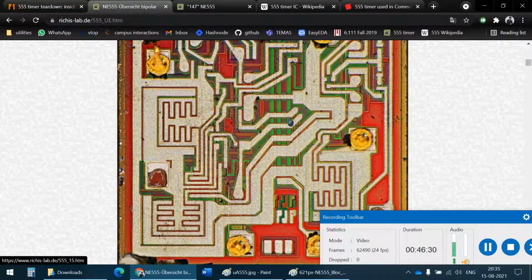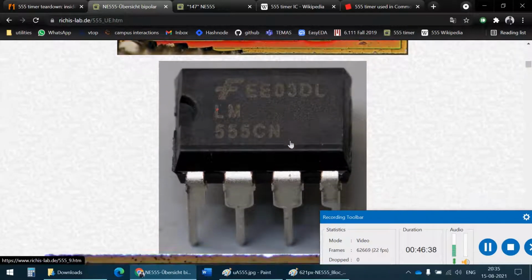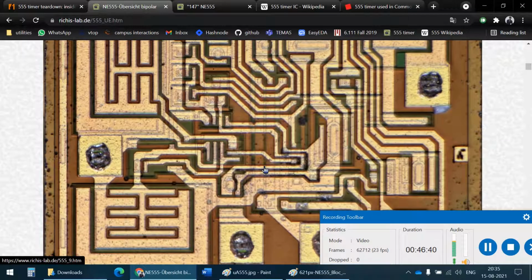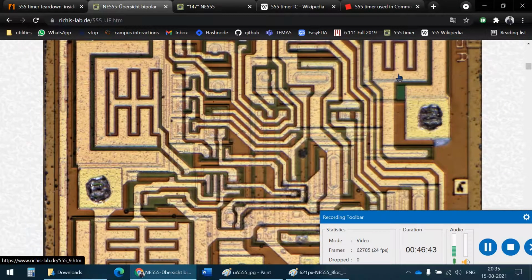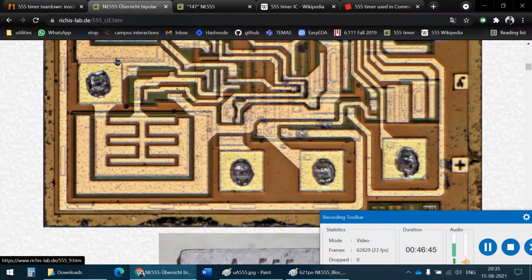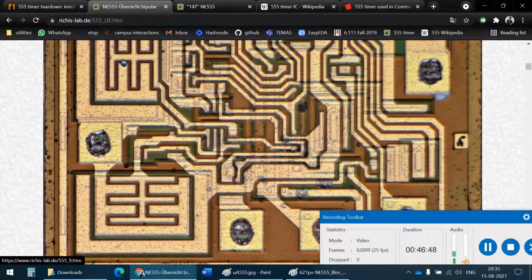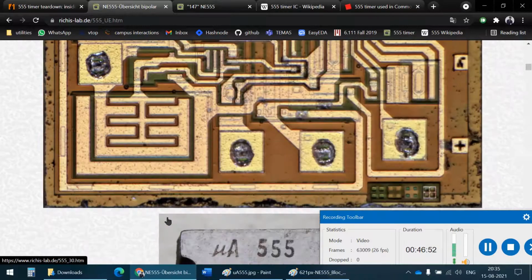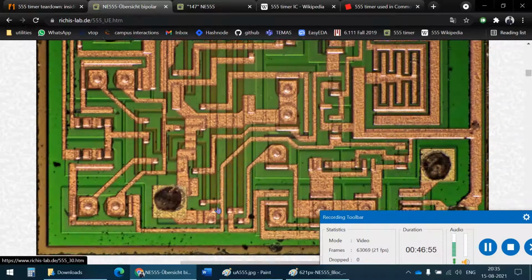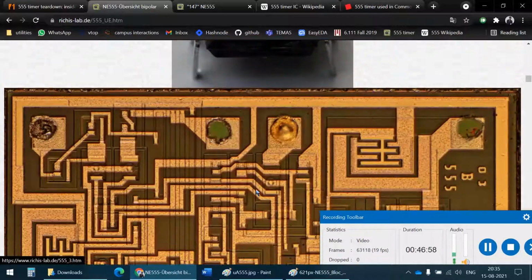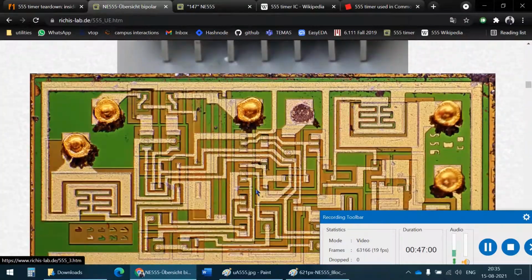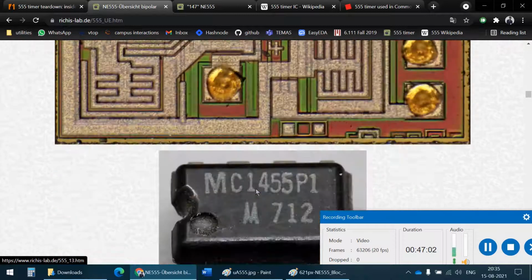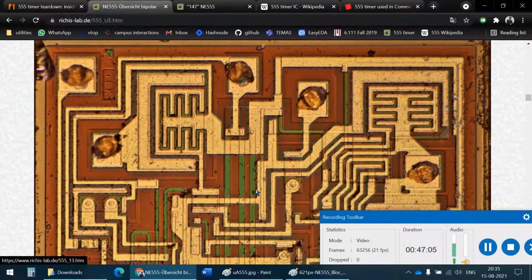Here it's because of the etching that it is connected. It's actually 3 long lines. The gaps are just because it got etched away. Again, same thing here. You can see the 1, 2, 3. This I would guess would be the output pin because it's connected to 2 transistors, one to turn it high and one to turn it low. So yeah, this is the chip we looked at. I think there's quite a few. You can take any one and go ahead and try and identify whatever you can from it.